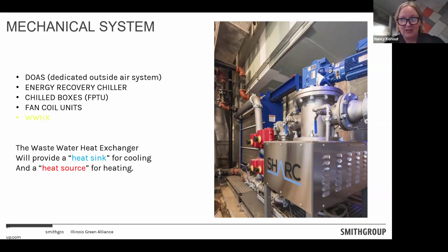So that's great, and it uses heat exchange as well with the exhaust air from the space. So it's not inefficient, and it's increasing ventilation. Then an energy recovery chiller, which is basically just a chiller that can generate hot and chilled water using the refrigeration cycle, extracting and rejecting heat from the fluid that goes through this Shark equipment.